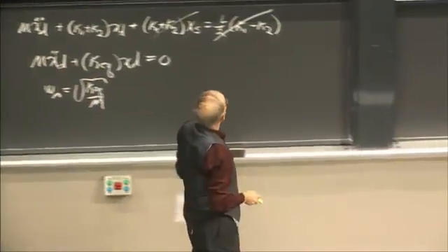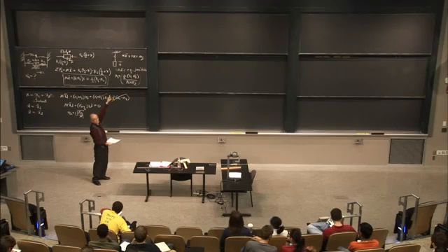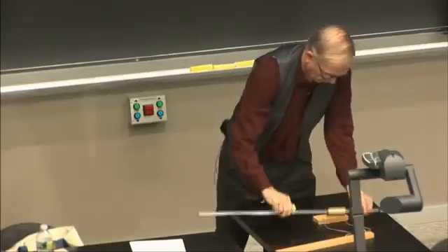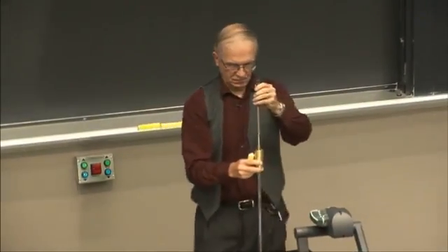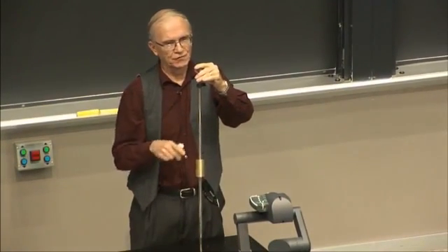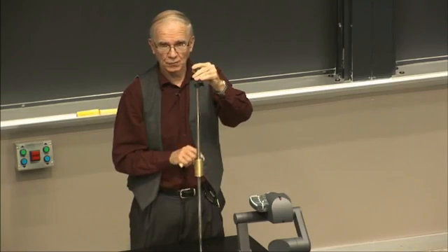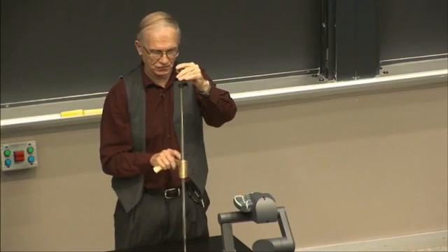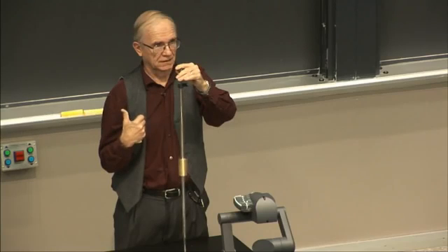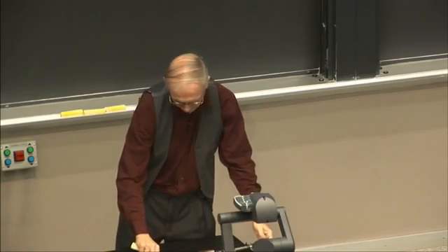Now, the same thing is true of that problem. That's a non-homogeneous differential equation for the hanging mass. We've derived the equations of motion for this many different ways, but we usually said zero spring force for this term. But now, if you started from here and said this is the static equilibrium position, what's the motion about this position? Then you'd get the equation with 0 on the right-hand side. Lots of advantages to using that.